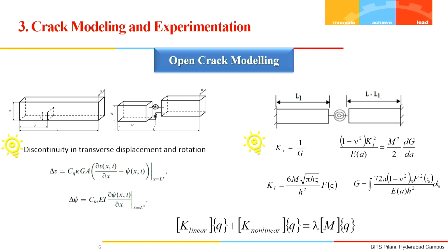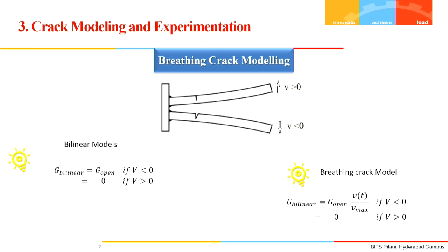This eigenvalue equation is nonlinear because the stiffness matrix here is nonlinear. And for the open crack, as we know that there is no time dependency of the stiffness, it is quite easier to solve. Any general equation, we give the solution of this equation, Newton-Raphson, Runge-Kutta, by any differential equation solver we'll get the eigenvalue problem, we can solve it. This equation we have particularly solved by just following an iterative technique. So we'll get the final response and we'll see how this crack affects the responses.